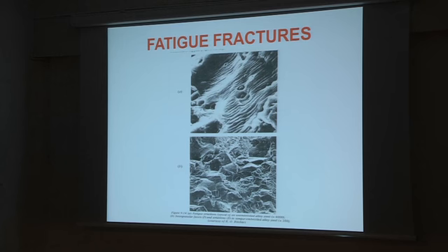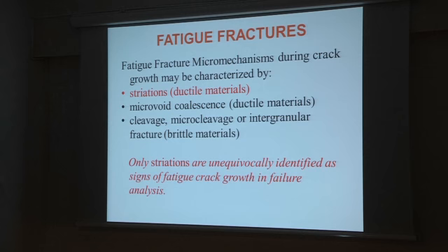But in ductile materials, you can have microvoid coalescence, and in brittle materials, in the case of fatigue, you may have cleavage, microcleavage, quasi cleavage, or intergranular fracture.